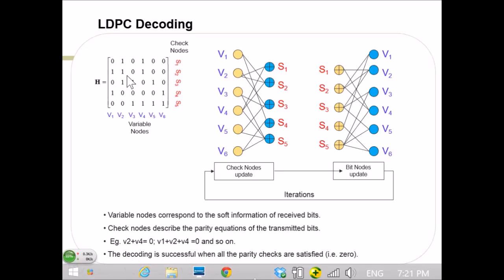Are you familiar with the DVB-S2 LDPC code? Yes. So what is the size of the H matrix? It is around 64K or something. It's 6400 by something. It has different rates basically, and also the circulant size is 360. For the rate 2/3.